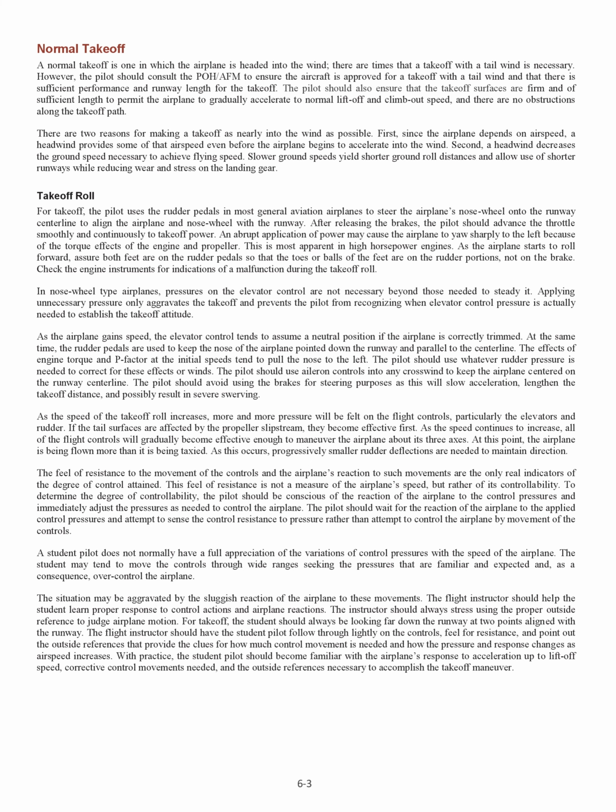The instructor should always stress using the proper outside reference to judge airplane motion. For takeoff, the student should always be looking far down the runway at 2 points aligned with the runway. The flight instructor should have the student pilot follow through lightly on the controls, feel for resistance, and point out the outside references that provide the clues for how much control movement is needed and how the pressure and response changes as airspeed increases. With practice, the student pilot should become familiar with the airplane's response to acceleration up to liftoff speed, corrective control movements needed, and the outside references necessary to accomplish the takeoff maneuver.